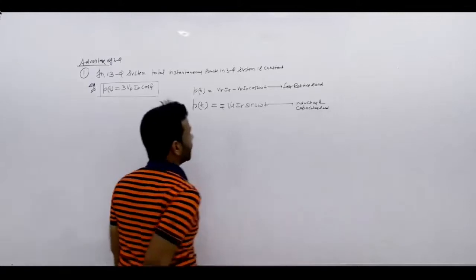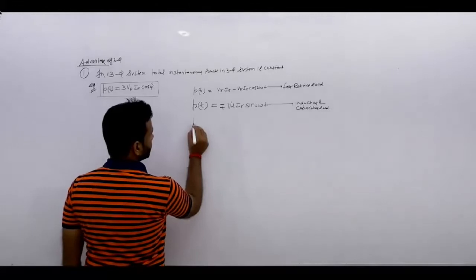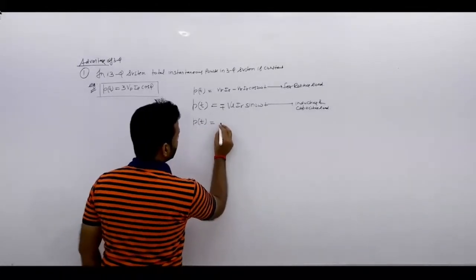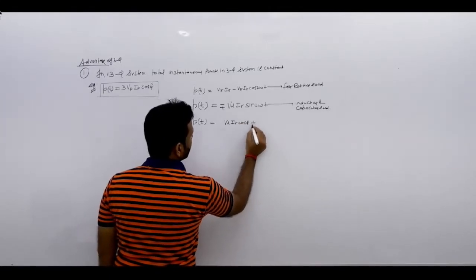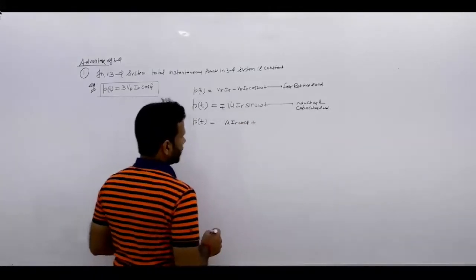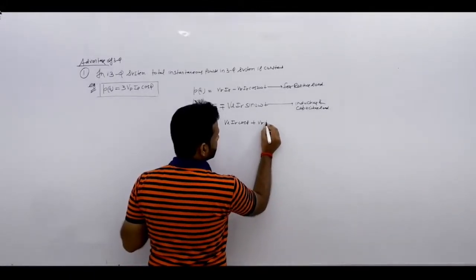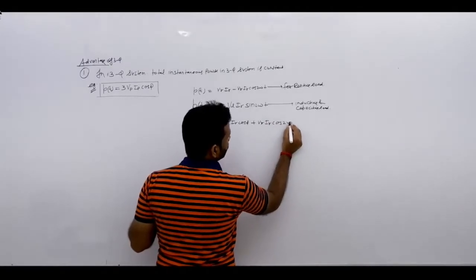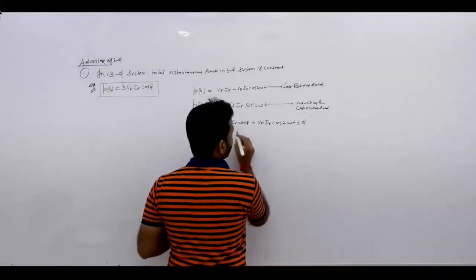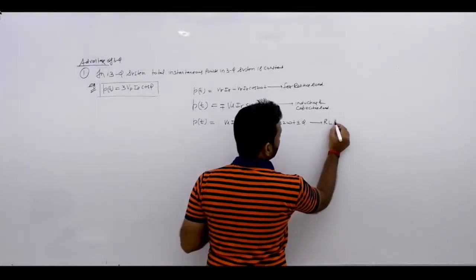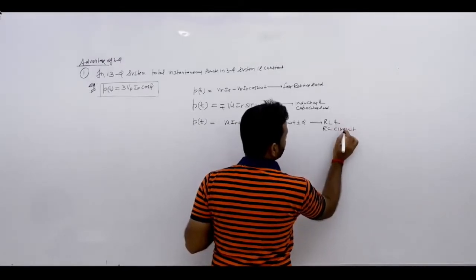Okay so far. Now if you see the RL series or RC series circuit, then PT, if you remember, is Vrms Irms cos phi plus or minus Vrms Irms cos (2 omega t plus or minus phi). It is for RL and RC circuits.